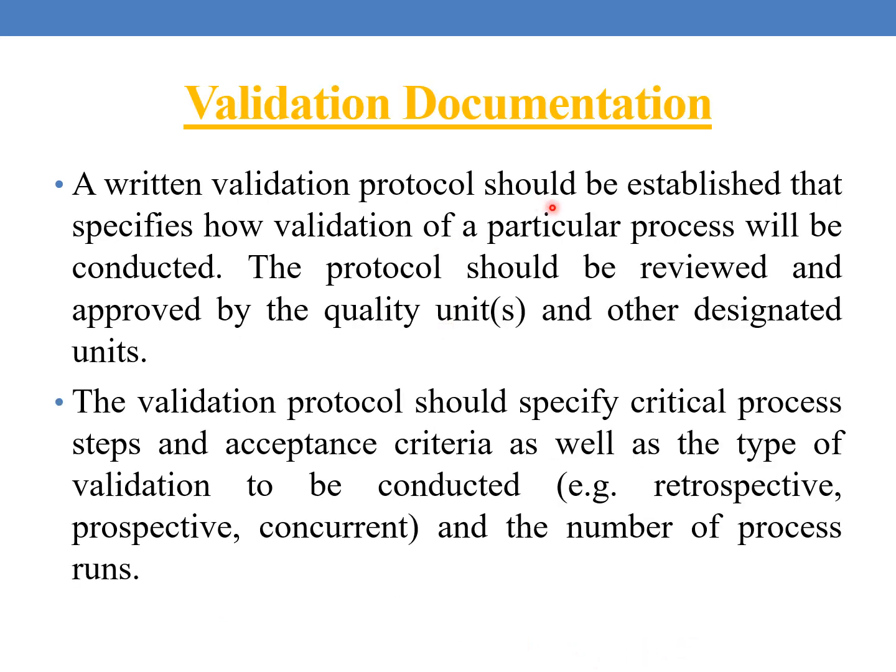Coming to validation documentation, a written validation protocol should be established that specifies how validation of a particular process will be conducted. The protocol should be reviewed and approved by the quality units and other designated units. The validation protocol should specify critical process steps and acceptance criteria as well as the type of validation to be conducted, that is, whether it is retrospective, prospective or concurrent, and the number of process runs.